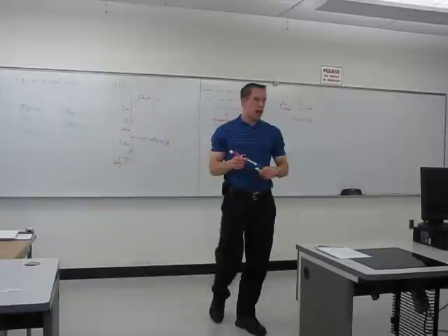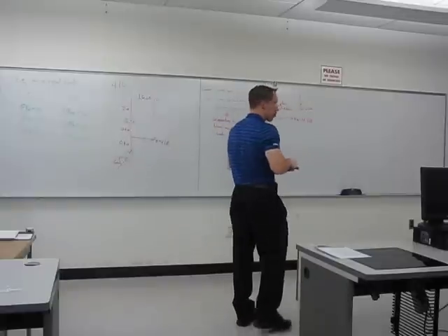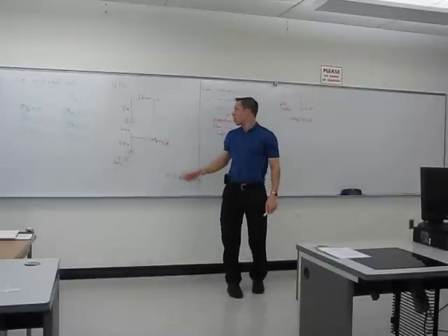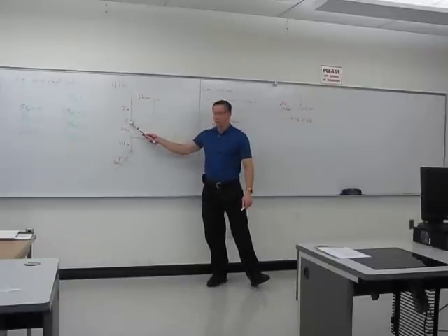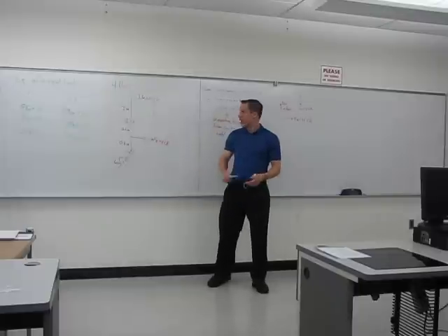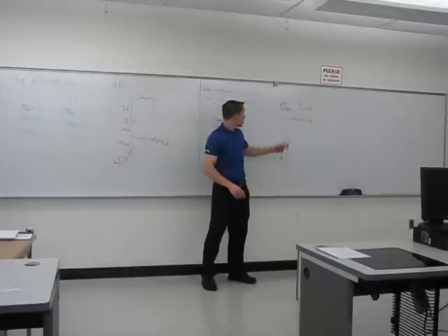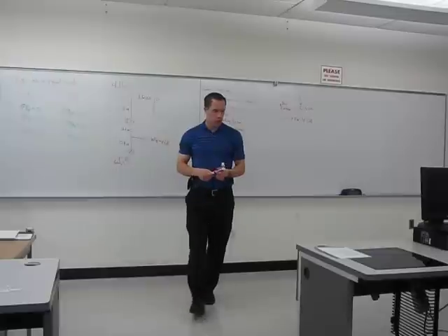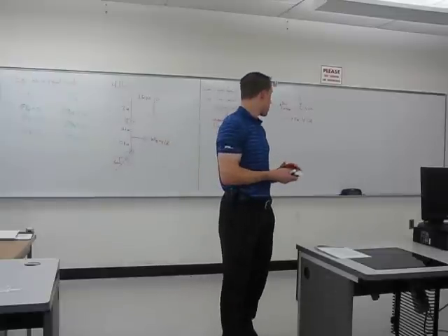But we have to be open to the possibility that we could have an X and a Y component for the reaction force due to this pin. So anytime you see one of these pins, you should just go ahead and label yourself an X and a Y force, an X and a Y component for the reaction force.